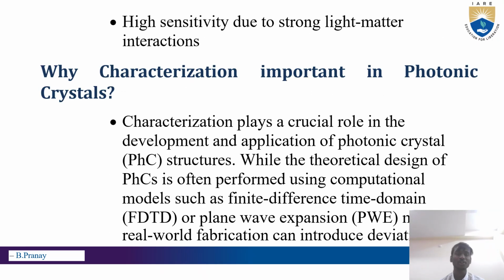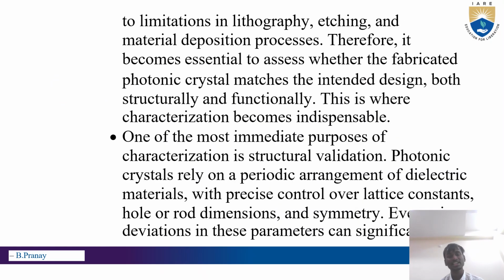Why is characterization important in photonic crystals? Characterization plays a crucial role in the development and application of photonic crystal structures. While the theoretical design of PhCs is often performed using computational models such as finite difference time domain or plane wave expansion, real world fabrication can include deviations due to limitations in lithography, etching and material deposition processes. Therefore, it becomes essential to assess whether the fabricated photonic crystal matches the intended design both structurally and functionally. This is where characterization becomes indispensable.